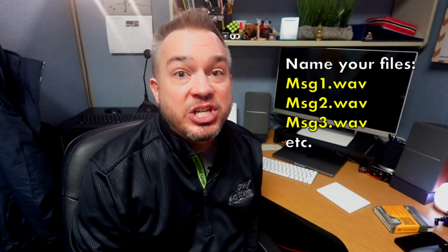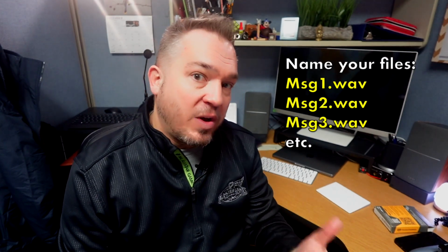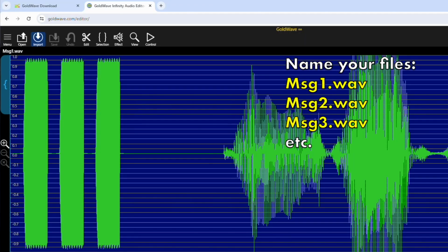The name of the file is important too. The announcer can play up to 16 different messages, and the way that those files are read in the system is according to how you name them. So message 1 should be labeled MSG1.wav. Message 2 would then be MSG2.wav, all the way up to 16.